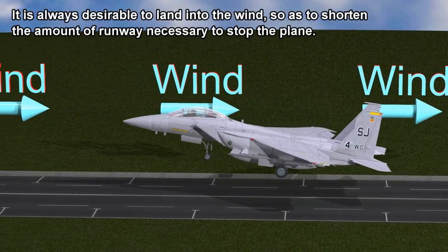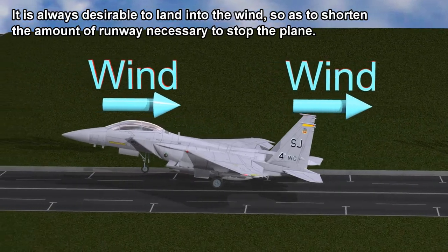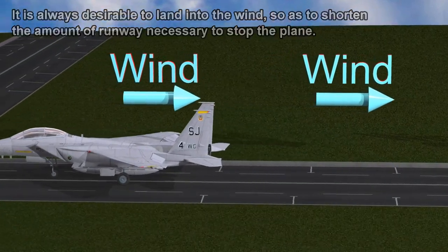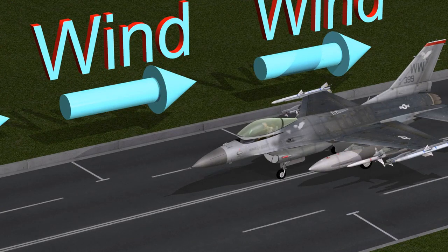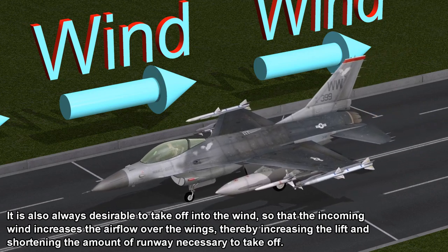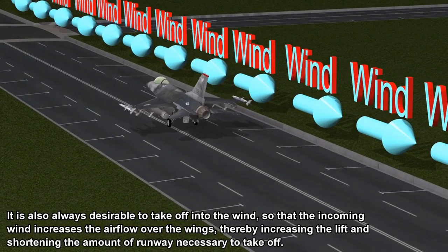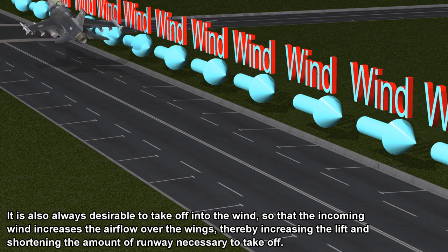It's always desirable to land into the wind, so as to shorten the amount of runway necessary to stop the plane. It's also always desirable to take off into the wind, so that the incoming wind increases the airflow over the wings, thereby increasing the lift and shortening the amount of runway necessary to take off.